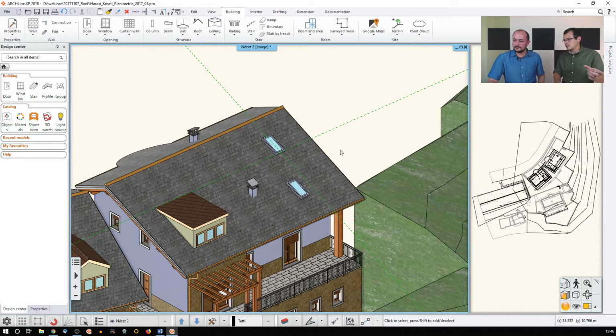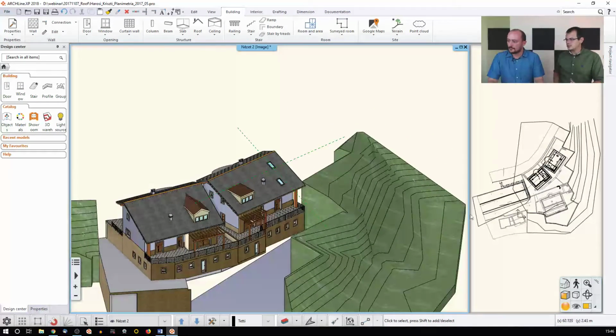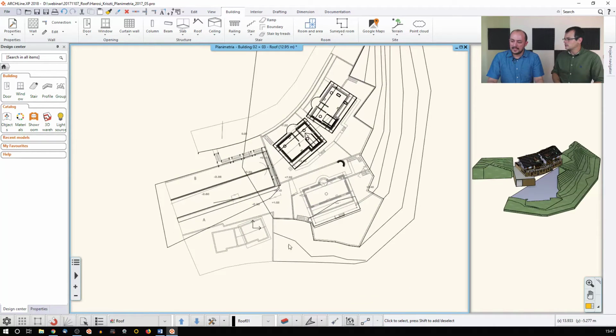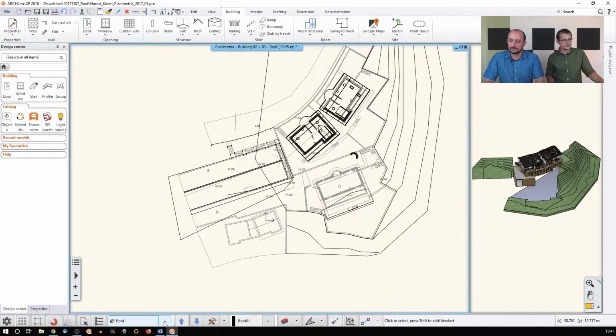We briefly talked about tiling, that what we see right now is just a conceptual stage, but if you want to get a listing out of it, you have to do it in a different way. So how is that different from what we are seeing right now? Well, with tiling, and this time again I'm going back to the small roofs, you will see it is literally creating tiles themselves, literal objects as tiles distributed along, and it will make the model quite heavy. It's because it adds a bunch more surfaces.